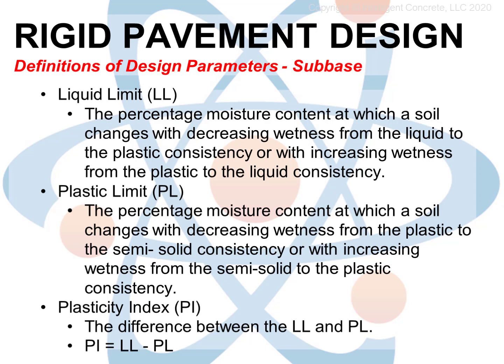Some soils never exhibit a plastic state. A high PI, say greater than 20 to 25, indicates that a soil could be much more susceptible to instability over a much greater range of soil moisture contents. Just remember this: a high plasticity index is bad, a low plasticity index is better.